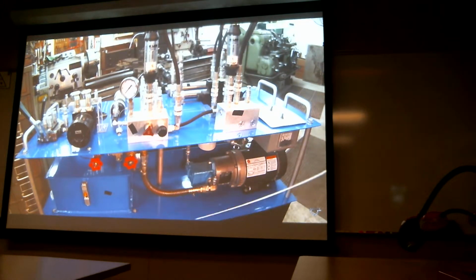All right, the last thing that we're going to talk about in the standard things that come in a hydraulic system is the fluid conductors, and that is your hoses and tubing and fittings and things like that. Of course, these components wouldn't do you any good unless they're actually hooked up and you have oil flowing through the system. Okay, so there's your inlet hose right there coming from your tank to your pump. Then you come out of your pump with this hose right here into this block here. Then you come with this hose right here into your directional valve. And here's your two work lines right here, your A and your B work line that go out to your hydraulic cylinder. And then here's your tank line that actually goes back through the filter to the tank.